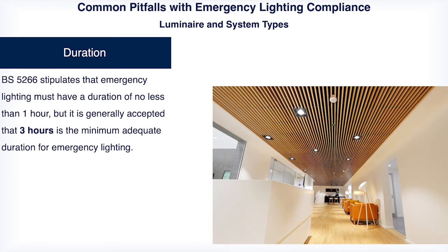So the duration, as I say, one key pitfall perhaps is the understanding of duration as far as the standard is concerned, because the code of practice stipulates that it must have a duration of not less than 1 hour. That's actually in the standard, but, as I said before, it's now generally accepted that 3 hours is the minimum adequate duration, and that's been commonly adopted by the industry, which obviously goes above and beyond the code of practice.